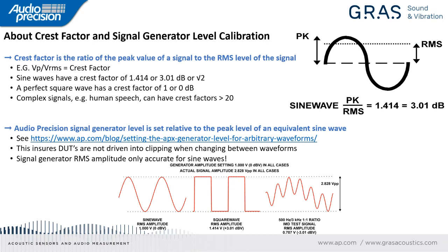And that's generally one thing I'll say that can be a problem with audio units, is that there are a lot of informal contractions in the world, and they create ambiguity. I'll say the most common one is where people say, oh, this is X volts. If you don't say whether it's volts RMS or volts peak or volts peak to peak, it is left to the interpretation of the reader to try and figure out what you mean from context. And dBA is very widely understood in the acoustics world, so I think a lot of people take it for granted, but it has the same sort of ambiguity.